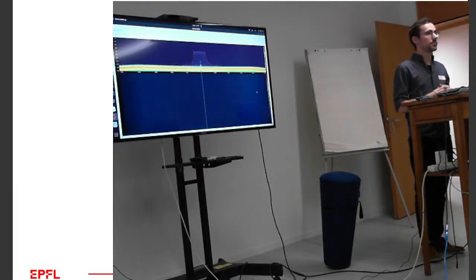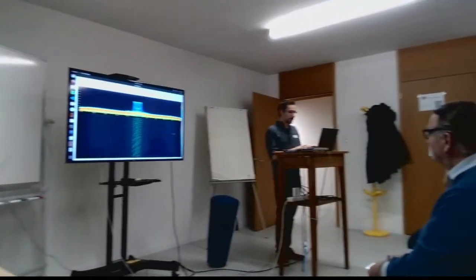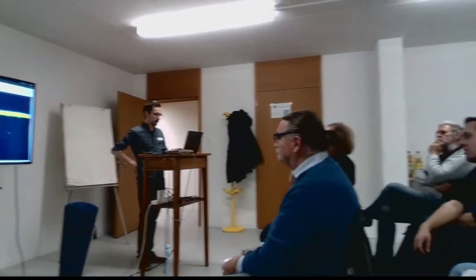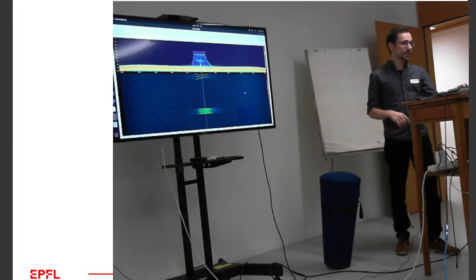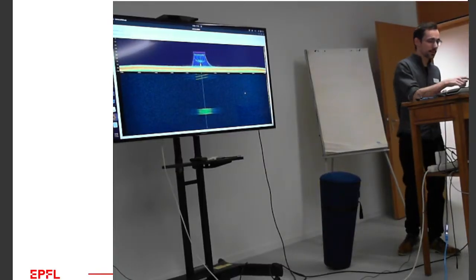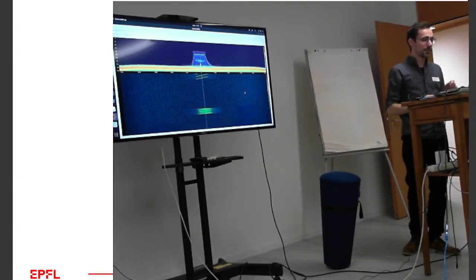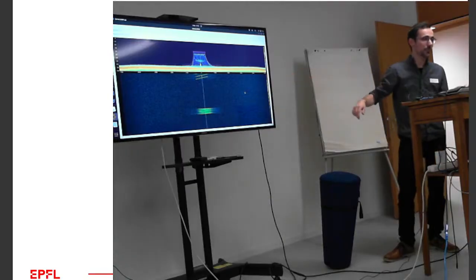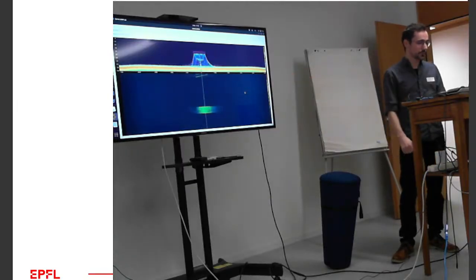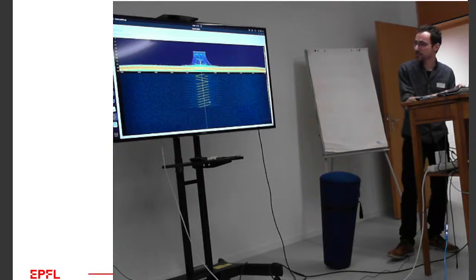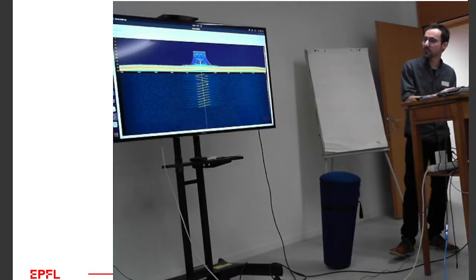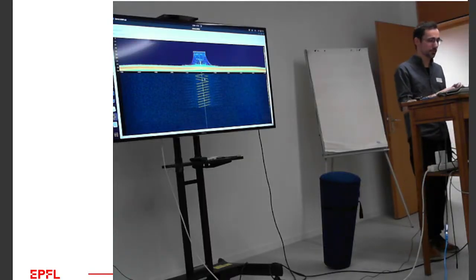Yes? I see the preamble as the first, I don't know, 12 lines or whatever, but there's also this blob that comes between the packets. What is that? That's the counter from... Oh, is it? No, I'm on a different frequency. That one is I sent both to show the difference of time for transmitting the same. But so there is the same content of information in the small blip as in the full one. And then you can clearly see, for those who know the preamble of LoRa, 8 repetitions of the same chirp and then 2.25 chirps going in the other direction.